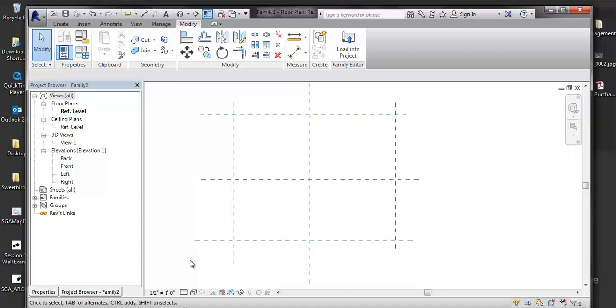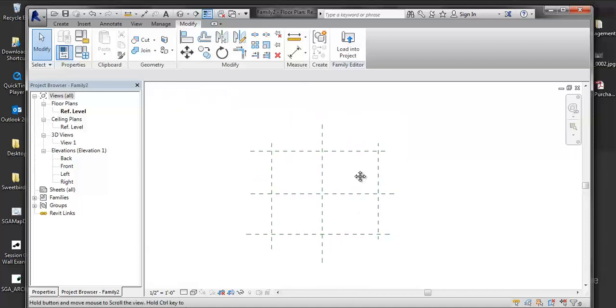In Grasshopper, I don't come in and immediately say that I'm going to have a box that says this and this, and then start scripting it. No, the idea is to be able to push and pull and iterate and drive different sets of design conditions, and that's kind of what we're setting up here. So the first and foremost easiest way to constrain these reference planes is by doing an equality constraint.